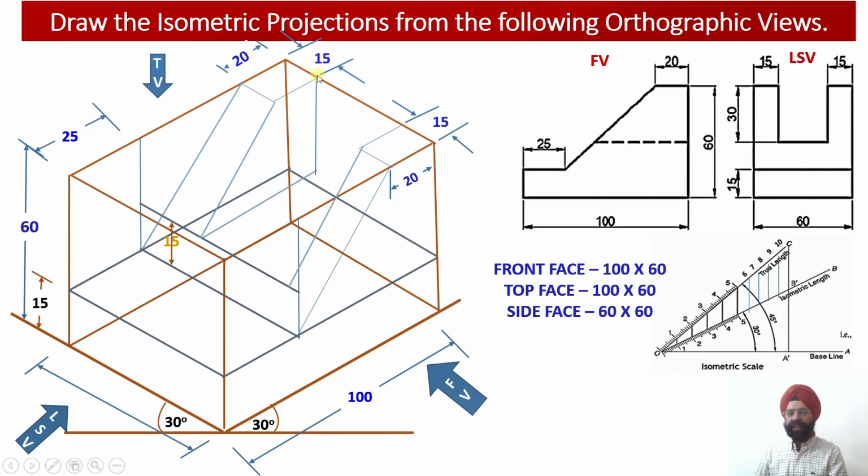Second method, I will be drawing a vertical edge equal to 30 millimeter parallel to the y-axis, and then draw an isometric line which will be parallel to the z-axis. So wherever this construction meets this inclined portion on the inner side of the web, this point of intersection, or this point and this point, these two points will be located. So by two methods we can locate it.